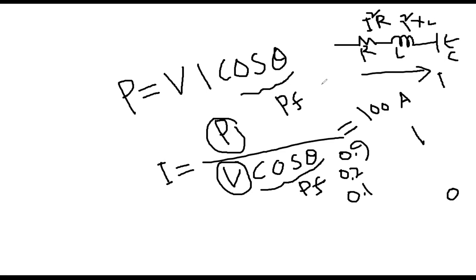And then because there is a higher value of current in this line, think about the voltage at this point and think about the voltage at this point. Let's say this is the VC point and this is the V0 point. Of course, there will be much more voltage drop here because high current is flowing. So all these components will cause voltage drop. On the other hand, when the power factor is higher, this means you have a low value of current, so there will be low loss and low voltage drop. So these are the impacts on the system.